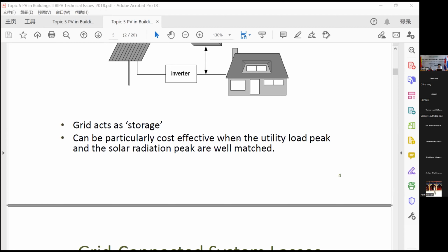In my opinion, or in my experience, the recycling problem of the silicon-based solar cell is similar to the purification. First of all, the silicon solar cell is not only silicon, we also have a lot of metals. We use aluminum and silver as the cathode and anode of the silicon solar cells, and how to extract these metals from the silicon is a problem.